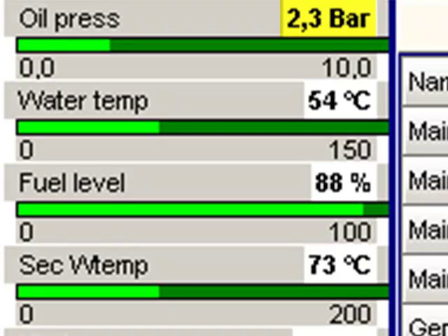The oil pressure value is the first register. The value is 17 in the hexadecimal system, and it is 23 in the decimal system. The registers list contains information that it has 1 decimal place. It means that I have read an oil pressure value of 2.3 bar.